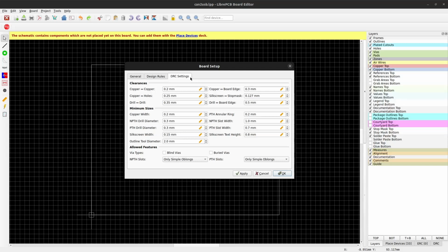Many PCB manufacturers list their capabilities on their website, at least the most important values like the minimum copper clearance and width. If you are not familiar with this task, don't worry too much about it. With the default values you should always be on the safe side and they are good enough for rather simple designs. Typically they only need to be adjusted for more complex designs.